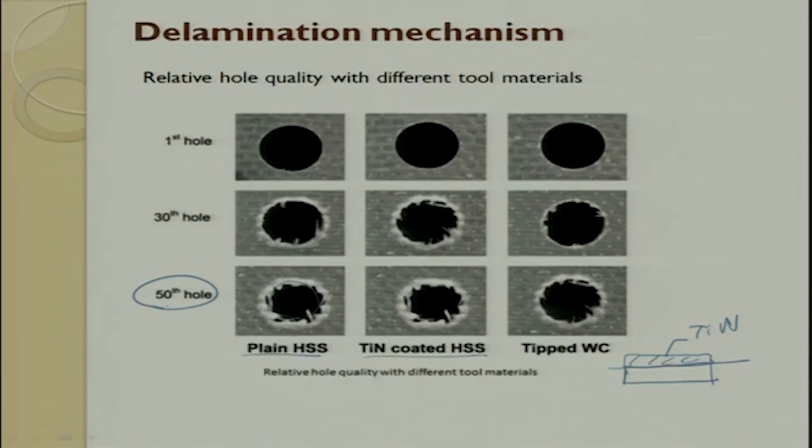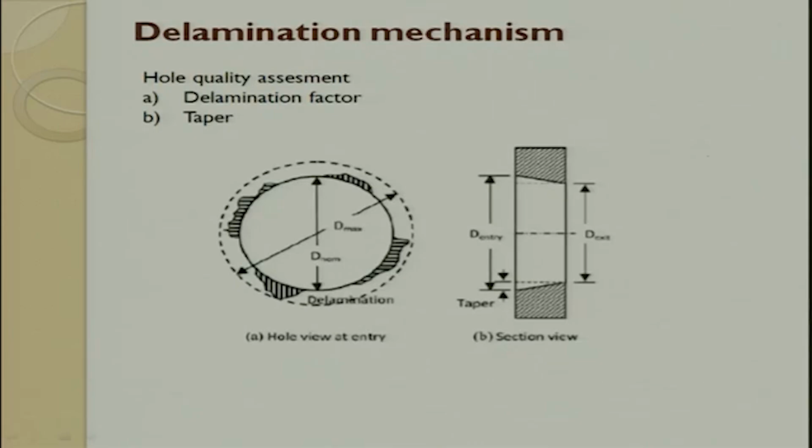That is why in the aero industry, when they have a large wing where they drill several holes, they just keep changing the drills after drilling 5 holes or 10 holes. They do not check all these things. They have established an experimental model, so for every 5 or 6 holes, they keep changing the drill and then keep going.